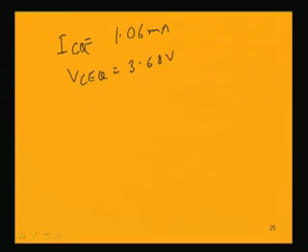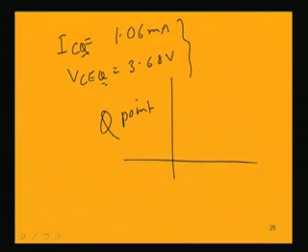You can check this calculation, and this will be the operating point Q. The Q is written in the subscript, meaning that these are the values for the DC condition, that is the Q point. This Q point you can find on the load line, where it will be either here or here or here. The location of the Q point is important.